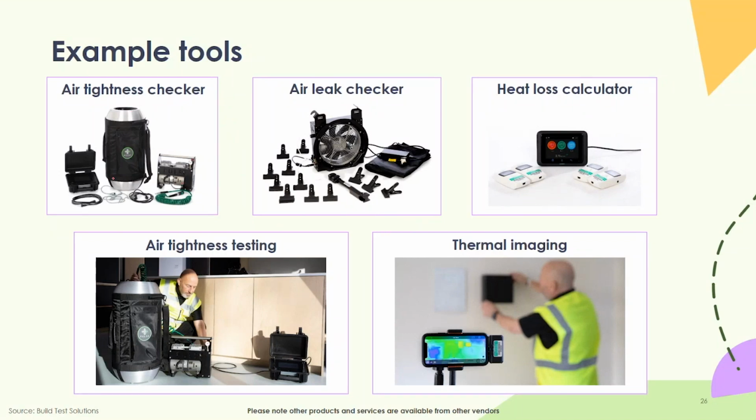So we've got the pulse air test method. The other alternative there would be the blower door fan, so a doorway mounted fan instead of this compressed air based system. Similar to a blower door fan, we've got this leak checker device, which can be window mounted to depressurize a building and help particularly site teams when on site find and address air leakage points and check draught stripping effectiveness and things.